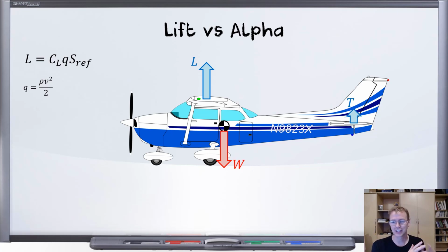If you've ever been watching the rocket launches lately, they often talk about max Q. The rocket is going through max Q right now. And now maybe you can see what they're talking about. As the rocket goes up, the density drops, simultaneously the velocity goes up, right? So the dropping density and the increasing velocity are fighting it out to see who's going to win as the Q varies. As that rocket goes up, the velocity is increasing, and that's causing Q to go up, but rho is dropping, and that's causing Q to go down. So, yeah, okay, so that's rockets. Maybe we'll get to rockets someday. But for us, I just want to use that to simplify my equation.